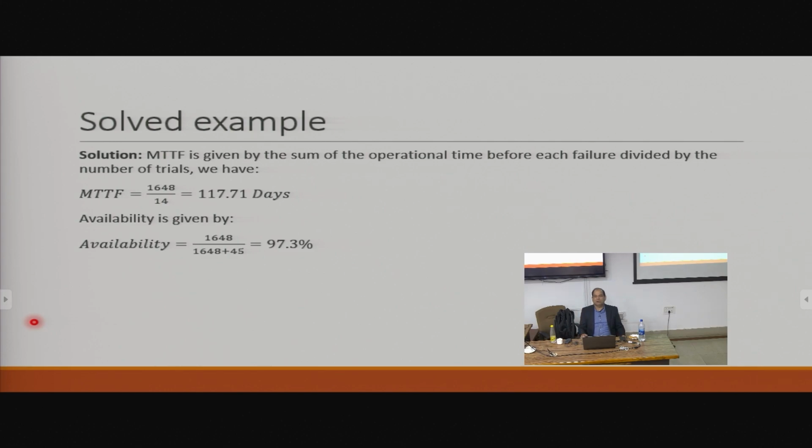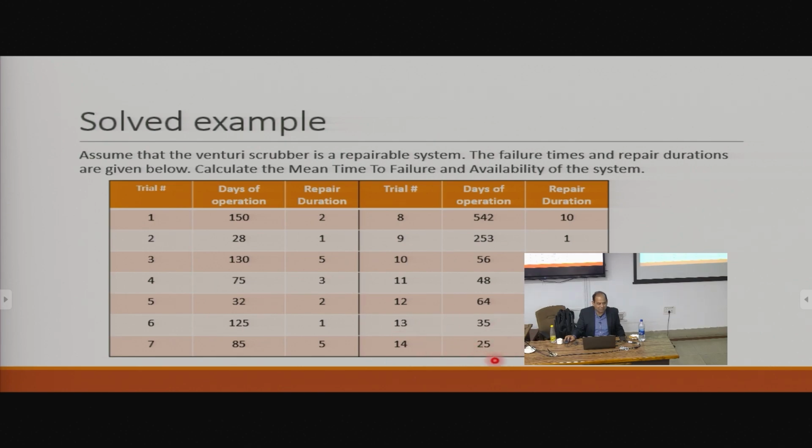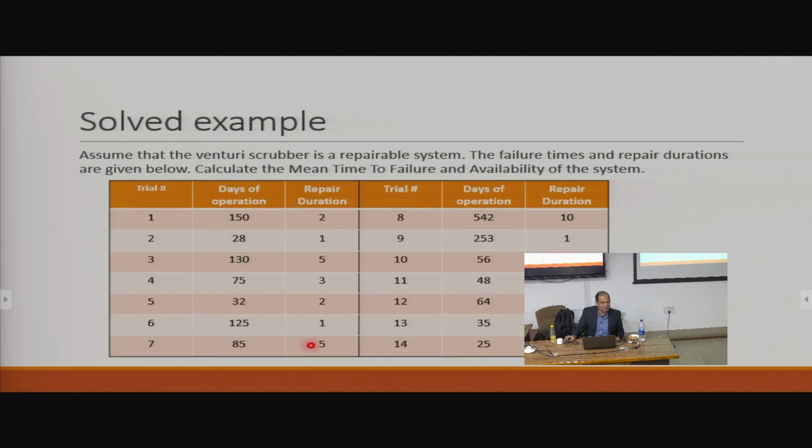And the collection of metrics that we talked about are minimum failure-free period, degradation information. So we know that this system here is probably not performing at the same level as this system here. Can we build other metrics into this? To distinguish that, this merges everything into one number. We're saying, no, look at this carefully and see what it's trying to tell us. Are you actually getting that MTTF? Is the system in the initial phases the same as the system at the later phases? So on and so forth, right? So I suggest creating a set of metrics and reporting all of them, not just these two, okay?